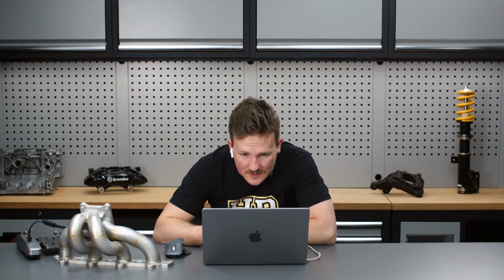Phil, how well does PeelCAD do for the centerline finding extrapolation? I haven't used it heaps, but I used it on this part, and from what I can see for tracing the centerline of an exhaust or something like that, or intercooler plumbing, or maybe even brake lines might be too small, but other plumbing in the vehicle, from what I can see, it works really well from my experience.